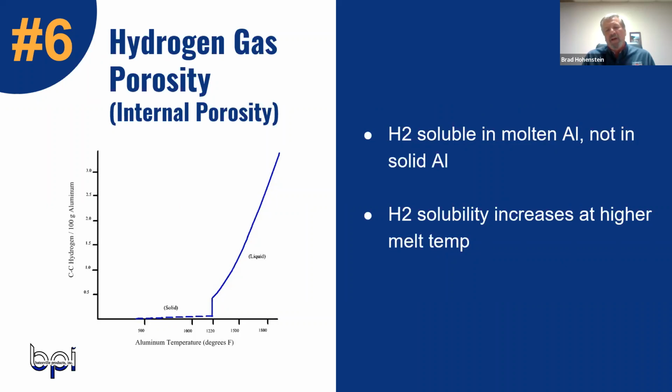The reaction that hydrogen has with the molten aluminum has two main factors. One is the moisture in the air: the higher the humidity, the faster the hydrogen is going to go in. Number two is the metal temperature. Over 1400 degrees, I think it's every 100 or 150 degrees after that, the rate that the hydrogen enters doubles. So typically that's why you want your casting temperature to be 1375, 1400 at the very top, if at all possible, because the higher the metal temperature and the more moisture in the air, the more hydrogen goes into the melt.